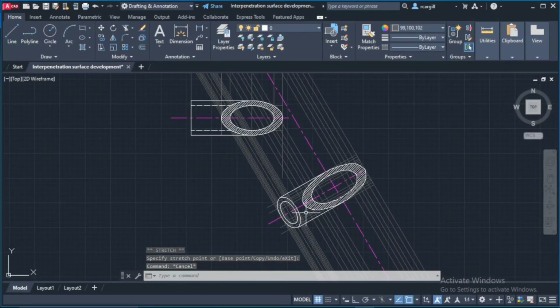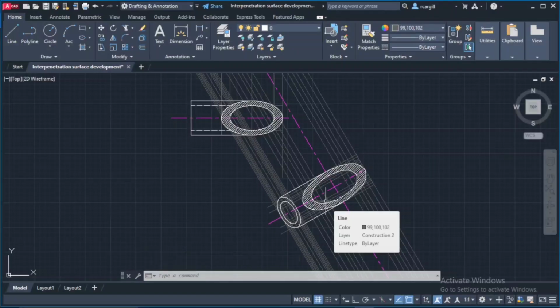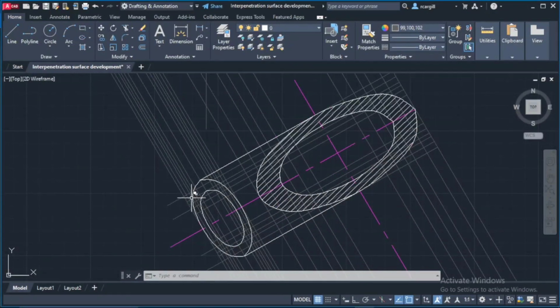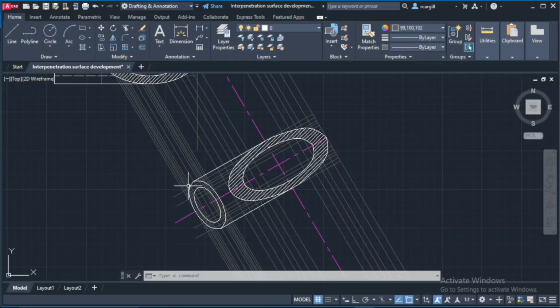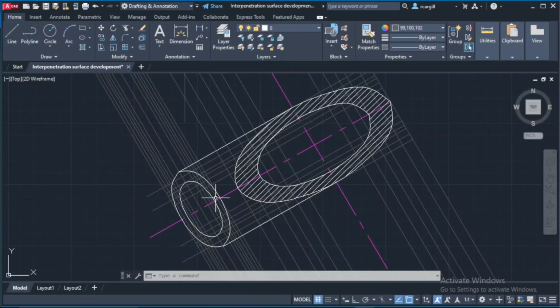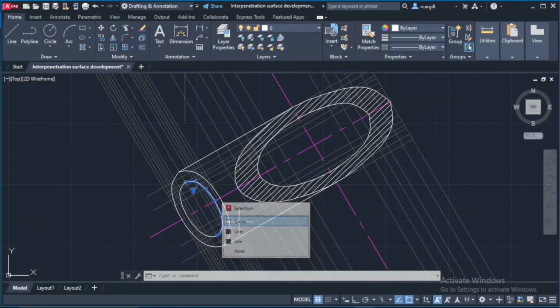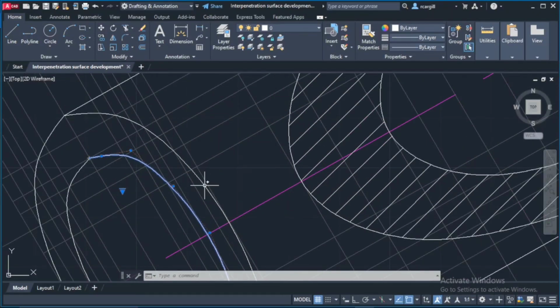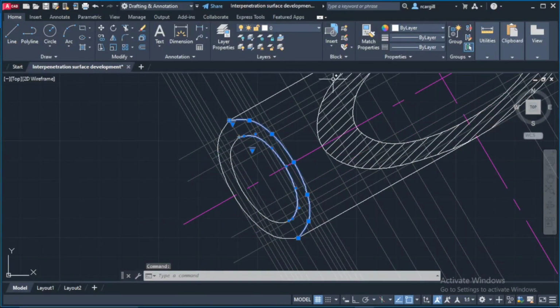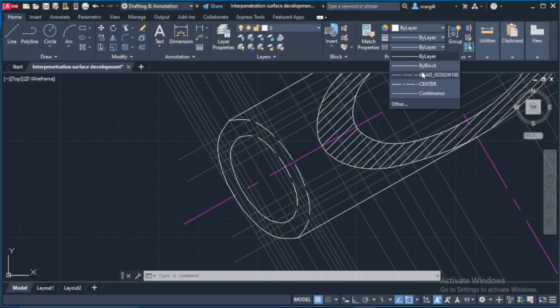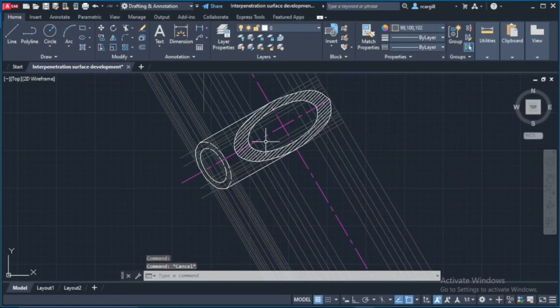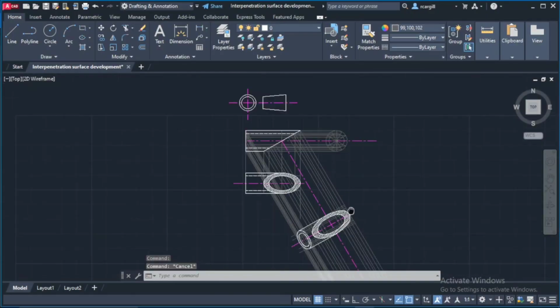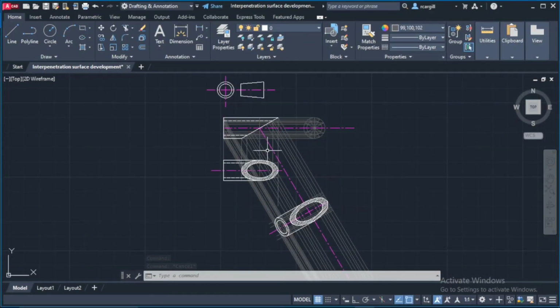That's our drawing complete. This is the complete auxiliary view, except for one thing. What we're seeing from where we're looking is we're seeing this end here, this part. But this next part is on the other side, so we're not seeing it. So because we're not seeing this line and we're not seeing this line, even though they're there, we have to represent those using broken lines. So what we're going to do is to change those to broken lines. And there we have it. That is the complete drawing. That would be all your marks. You just need to dimension, and that's it.